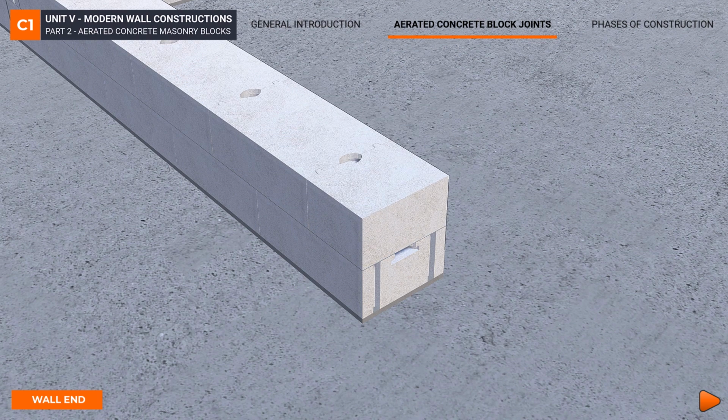In our example, we could use whole blocks for the masonry, because the span length was a multiple of the block length, 120 centimeters or 180 centimeters. If the corner points are closer or farther away, cut blocks are used and placed in the middle of the wall. In the meantime, you should avoid using blocks shorter than 12.5 centimeters. This can be avoided using 2 cut blocks per course instead of 1.